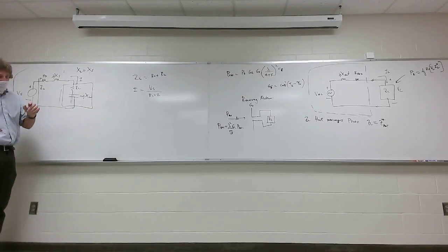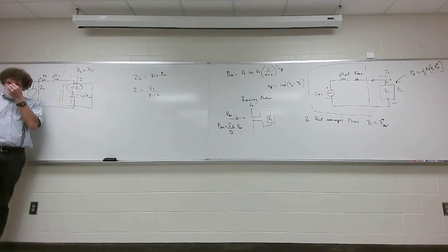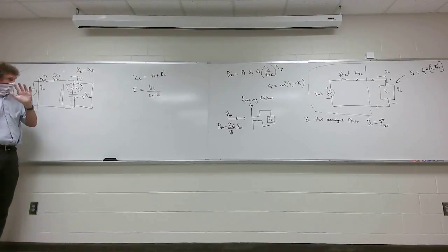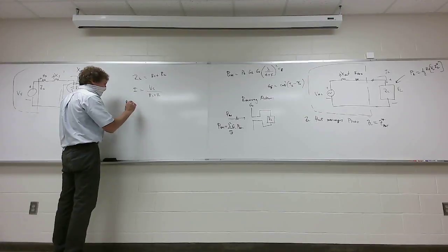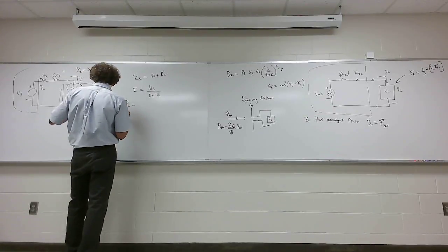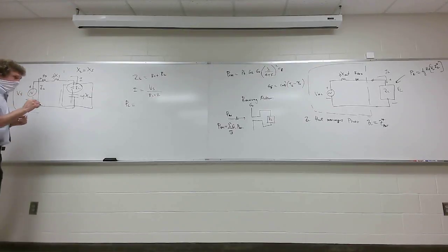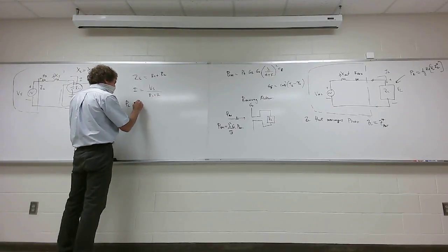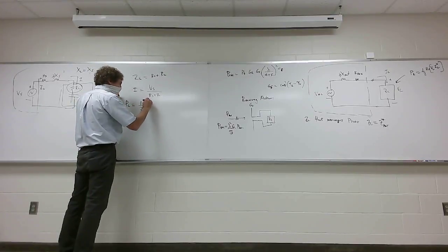So here, if I wanted the power, that resistor is the only thing in the load that dissipates power. Do we agree on that? And this is only load power. So power in the load, remember that's a resistor, and this is AC, so that Vs is like the peak voltage, would be 1/2 I magnitude squared times R load.